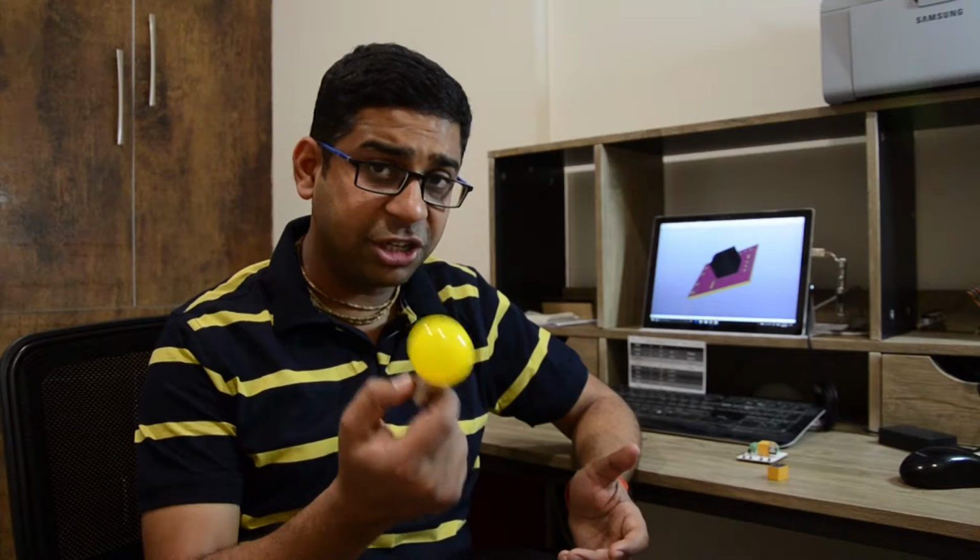Now let's say instead of this LED bulb, I had something else which was much more complex and can have a short circuit within it. I would not want my complex electronic circuit to fry just because there was a short circuit in the controlled appliance. So to isolate them and to be able to control appliances which require higher voltages and currents, we use something called a relay. A relay has an electric coil in it, and a metallic strip, which helps in switching on and off a circuit based on whether you have given a voltage to the coil inside it or not. We will look at that in detail right now.